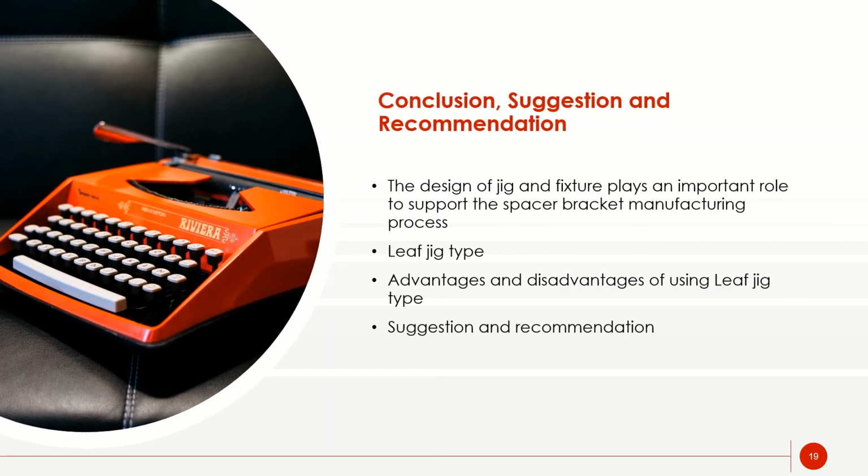So this is my conclusion, suggestion and recommendation. In conclusion, the design of jigs and fixtures plays an important role in supporting the spacer bracket manufacturing process. The overall considerations for the design of jigs and fixtures are shape, material and workpiece condition, pre-machined surface resistance, type of operation and machine instrument, and not forgetting the handling of the workpiece, ergonomics and safety aspects.